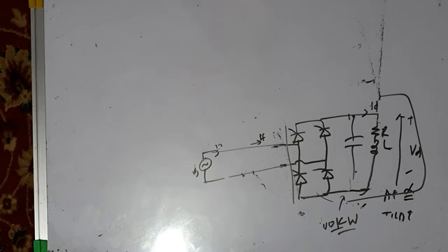And to solve these problems, first they came up with the solution of passive filters. But they found that so many single tuned filters are required, which will make the system bulky, heavy, costly. And then passive filters have other drawbacks, which we have discussed in one of the previous classes, like fixed compensation. They may detune if the system conditions change.